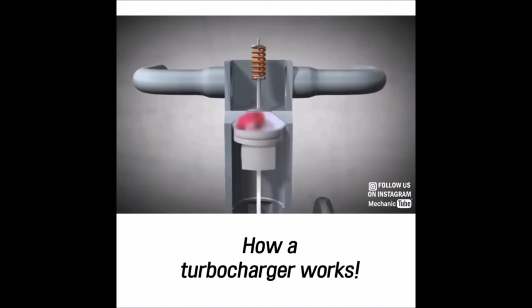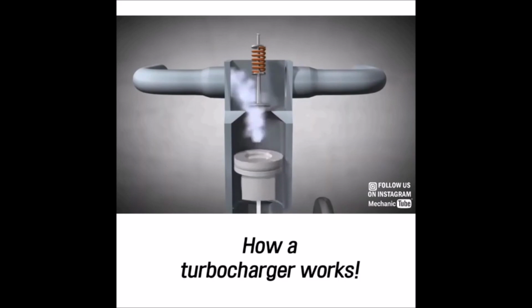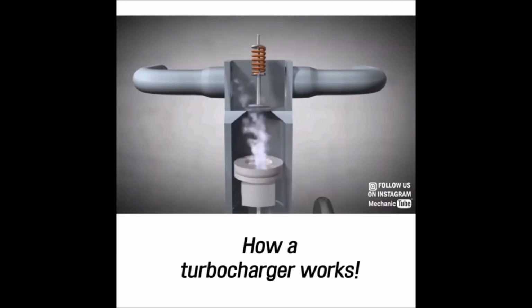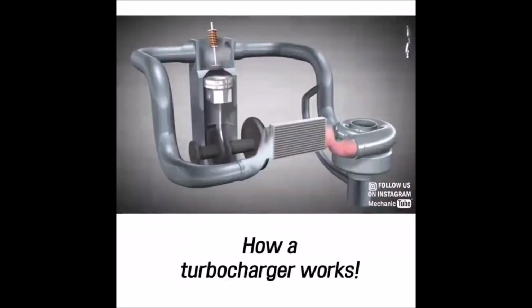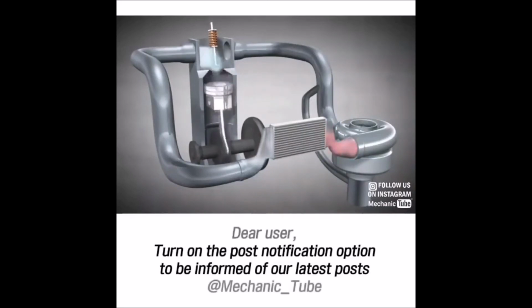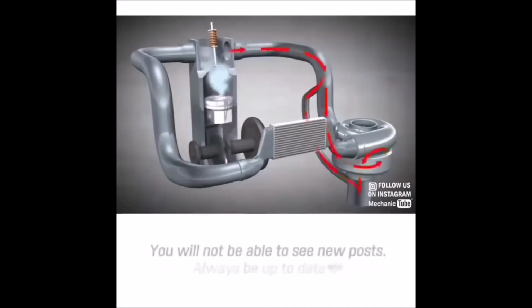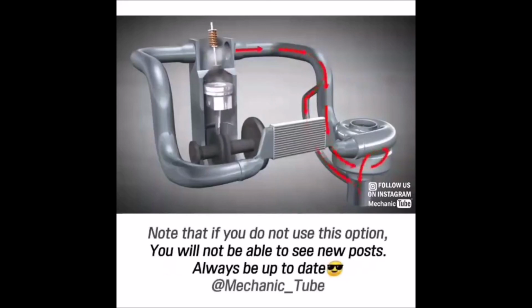At times of high RPM, for example on the highway, the atmospheric pressure will not push enough air into the cylinder. Consequently, the engine cannot run efficiently. The turbo makes the engine much more efficient. Furthermore, a valve, which is also known as a wastegate, is used to divert exhaust gas away from the turbine when too much exhaust gas is produced by the engine. So it limits the rotational speed of the turbine wheel and consequently the compressor wheel so that the turbocharger won't be damaged.